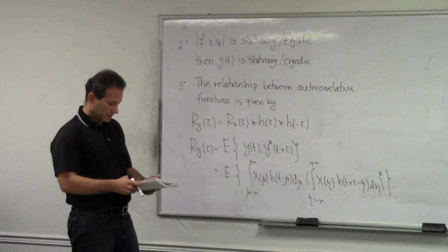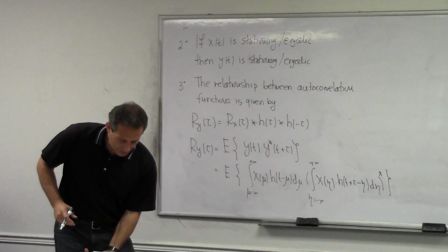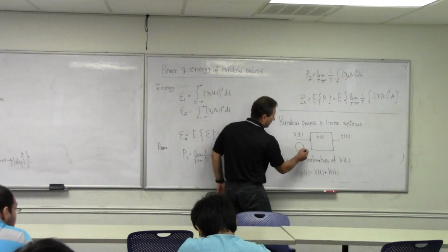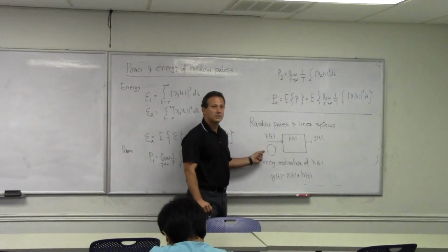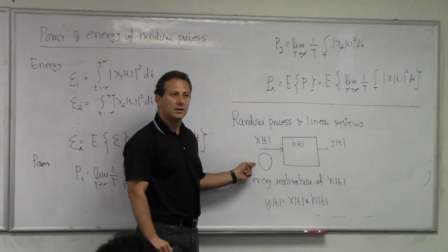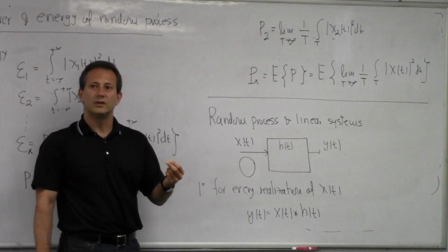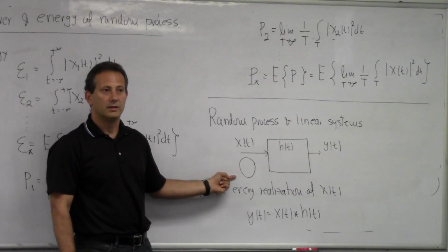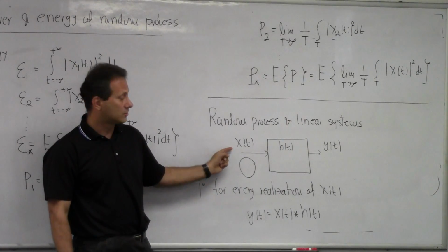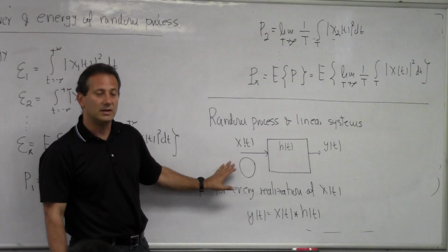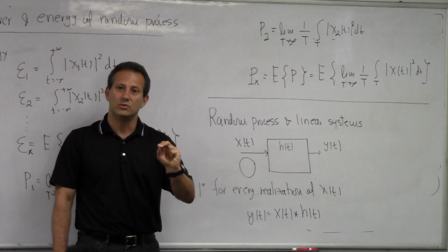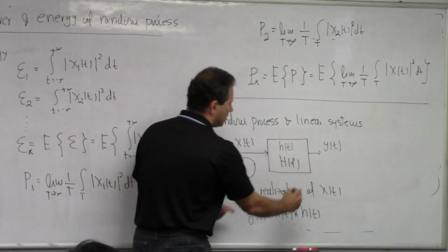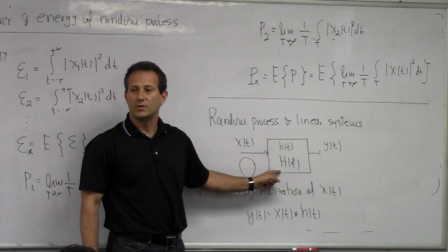So these are the three properties that I want to point out here. Now, what is missing, and this is an important thing that we need to define, is this bottom piece. I need to understand how I characterize my random process in the frequency domain, right? You see that that part is missing. We know how to do that for deterministic signals. How do I characterize a deterministic signal in the frequency domain? Taking the Fourier transform of the signal itself. So that part is missing here for random processes. I need to understand what sinusoids I need to use to build a particular random process. Now, this one I'm okay with. I know that to the impulse response I can attach the frequency response, which are Fourier transform pairs.